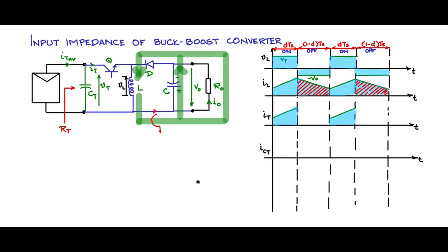Now that is actually composed of IC current and I0 current. So therefore it is I0 plus IC. I0 is the DC component, an average component of the current. IC does not have an average component, so it is a component of the current here, which is an AC component without average. So approximately I0 would look like this, plus IC would look something like this.